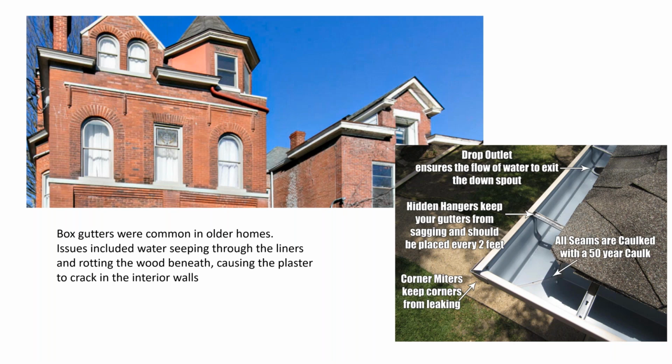You will see a lot of houses that have no overhang, and these gutters sit right up against the brick. That's a recipe for disaster if you don't keep your gutters clean. Again, water is your biggest threat with a house.